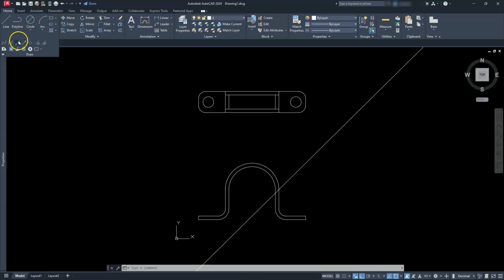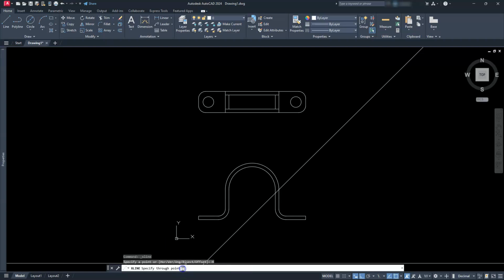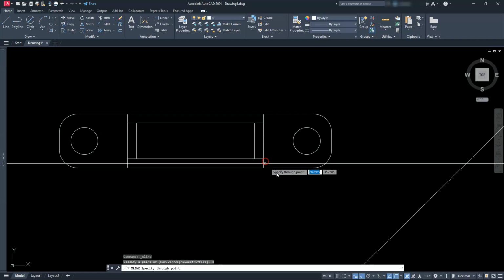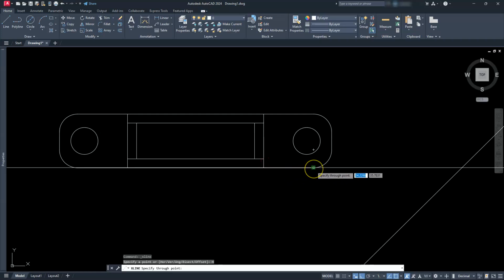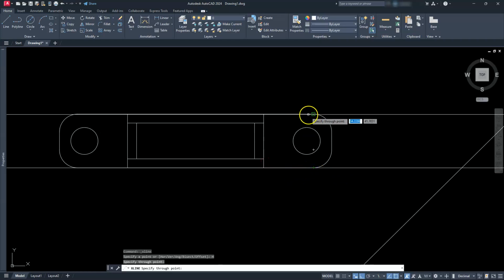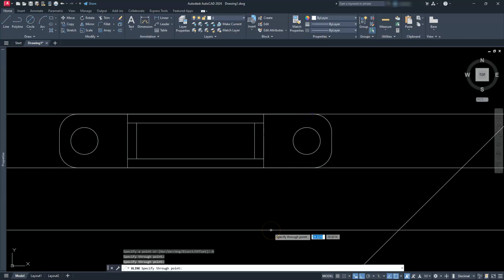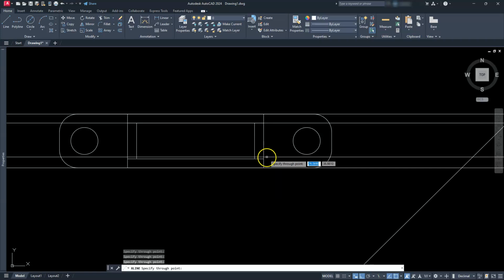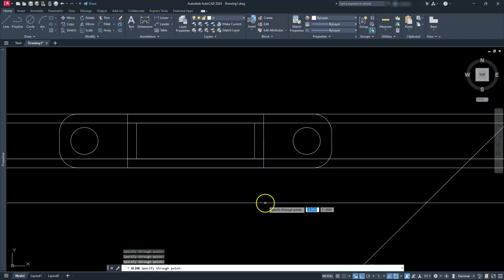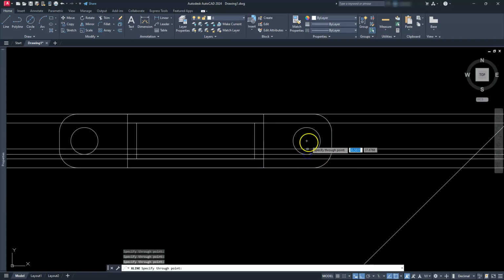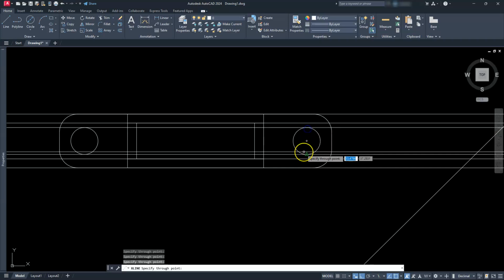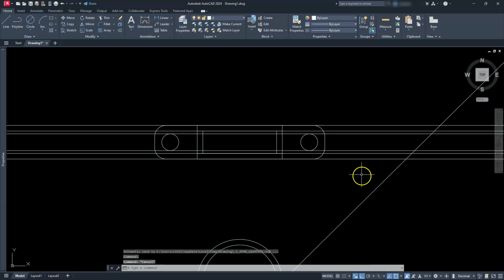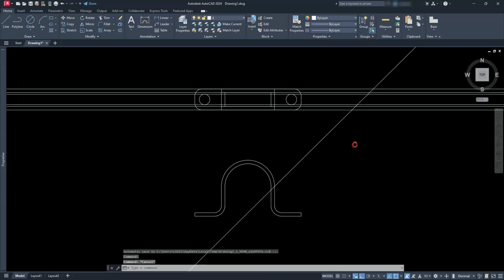Let's go and choose a construction line. Let's choose horizontal. And then I'm going to go ahead and track the horizontal lines that I need off of my miter line here, right? So I'm just going to go from that endpoint to that endpoint. I'm trying not to clutter it up with too much stuff, but I'm just going to go with these lines here. And then I think I may be able to get away with actually these two lines here as well. So I got quite a few miter lines going here.